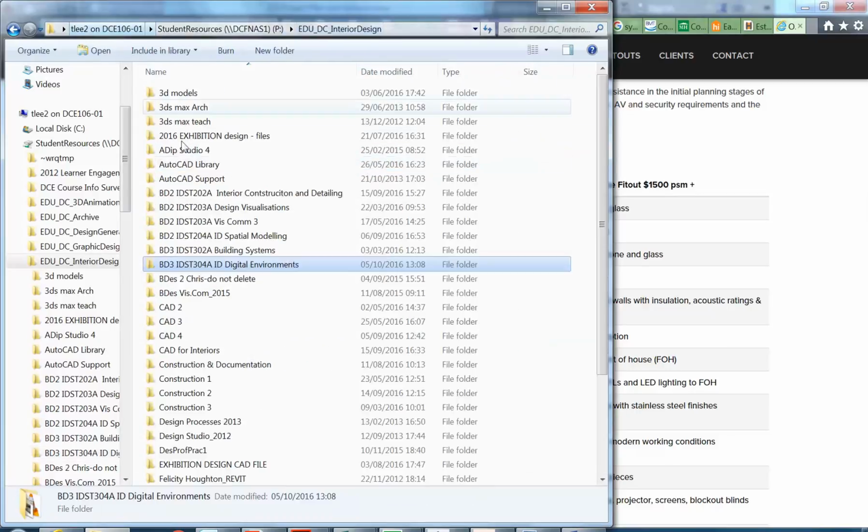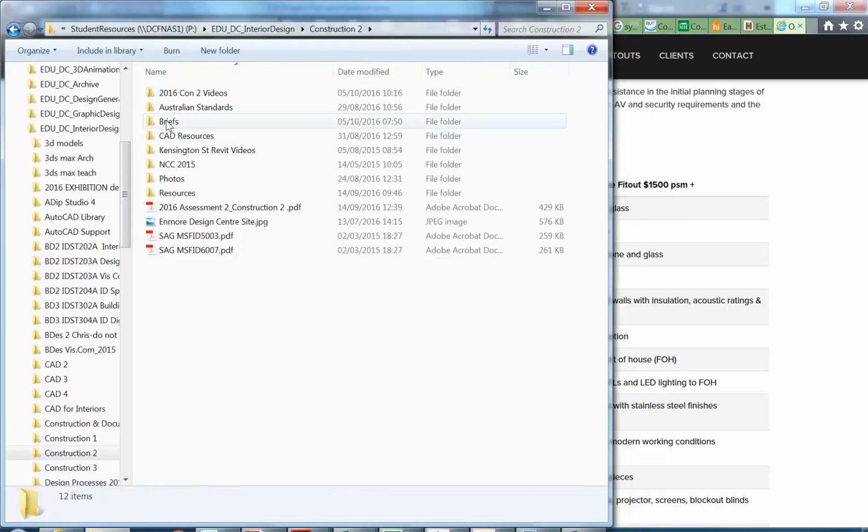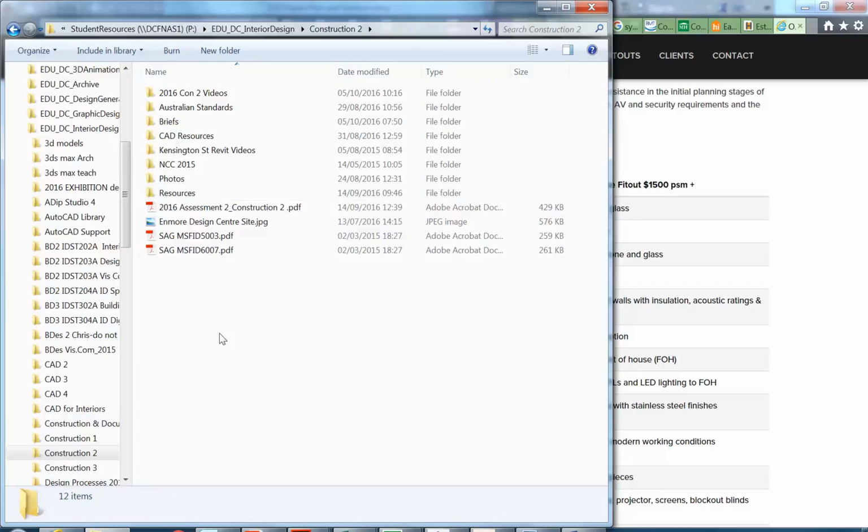And I've given you a template that you can use to do that more detailed costing, and that's really what you need to start on for this second assignment. So you do that rough square metre costing. Remember, it doesn't even include things like the height, so that square metre rate is the same regardless of the, in this case, the floor to ceiling height that we'd have in this space. Many apartments would be lower than this, some would be higher, and that doesn't take that into account at all. So it is just rough.